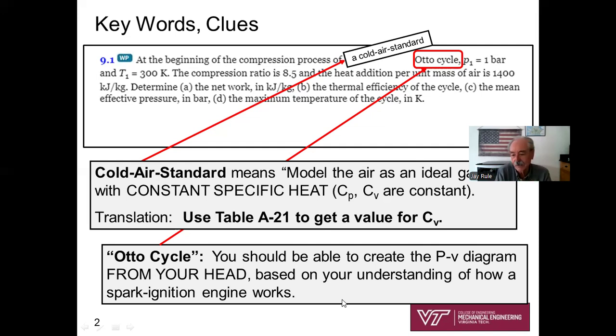Otto cycle, just like previous, you should be able to create the PV diagram from your head for the Otto cycle based on your understanding of how a spark ignition engine works. And here, again, I'm going to try to quickly go through and explain how you can generate this pressure specific volume diagram basically from your head, knowing just some basics about a spark ignition engine.